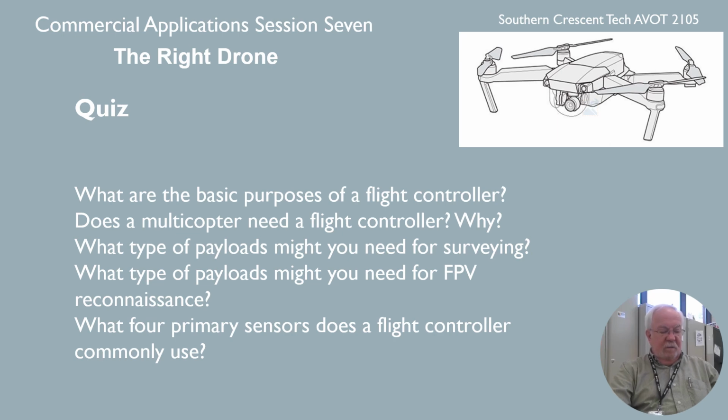What primary sensors do flight controllers require to operate? Okay, well, inertial measurement units, IMUs, power management units, PMUs, some kind of range sensor or optical flow, LiDAR kind of optical sensing for landing and knowing when to shut the motors off when it does land. So that's typically what's on most of these drones.